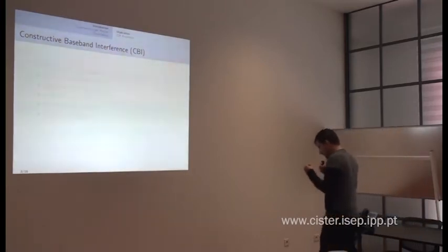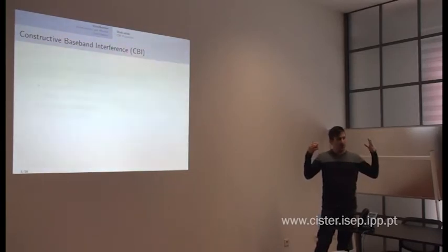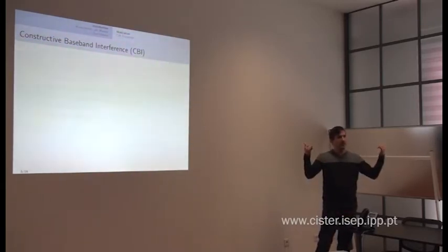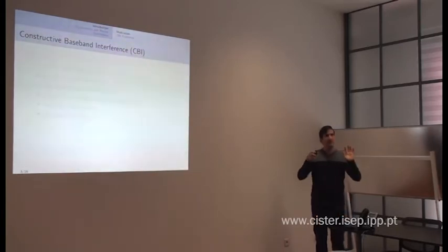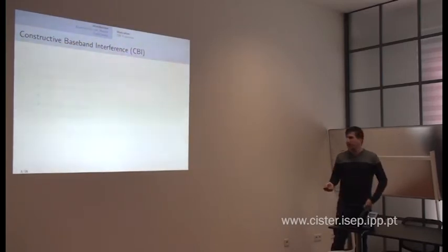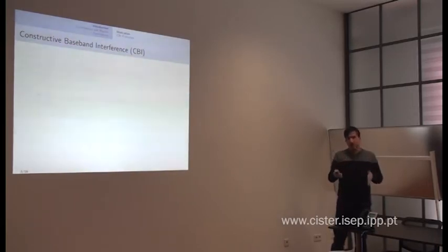When we think of using this to convey certain information, it will be convenient that all these nodes that are transmitting have some sort of time synchronization, and that the information they transmit is exactly the same. Otherwise, we will have all kinds of problems. So when we speak about constructive baseband interference, what we're saying is that the baseband signal transmitted from all these nodes is exactly the same, and of course, time synchronized accurately enough so that it's going to be constructive at the receiver.